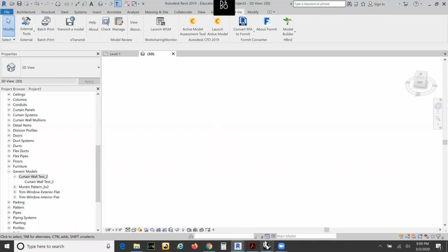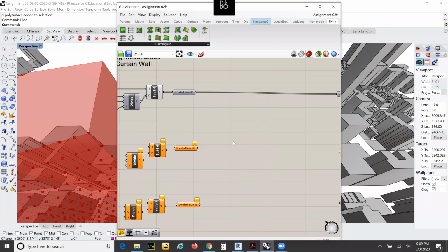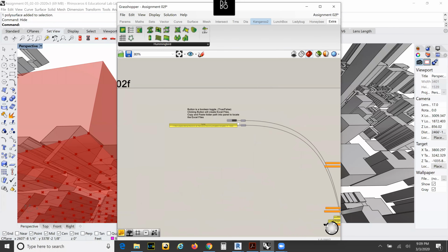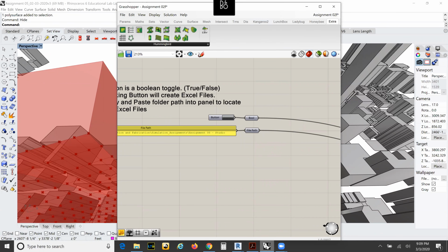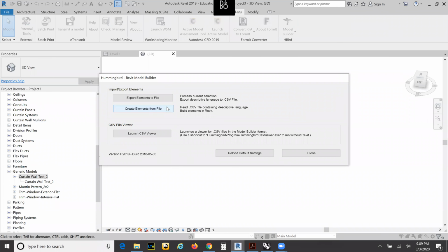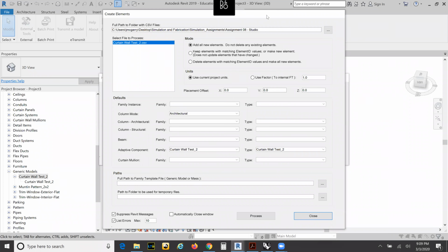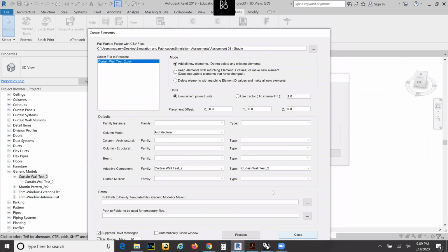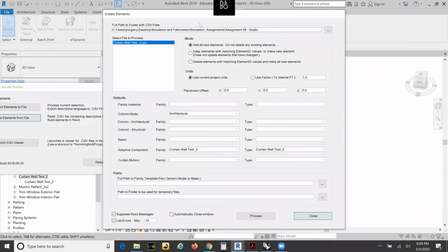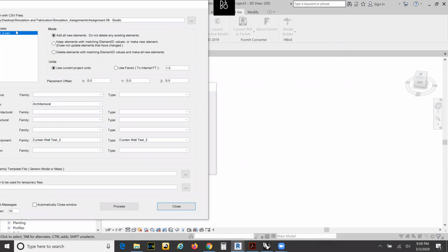Is it great for one, two, three time views? Yes. And when you don't have a whole lot of annotations to do, it's great. But as soon as you get pretty far ahead and you have some dimension strings and you have to start redoing some of your work, then it's not too good. But it's still a fantastic tool to get some complicated shapes in there and get them very close to your Grasshopper script. And the nice thing is when we click the button again, it just saves right over this, and we can run it again.